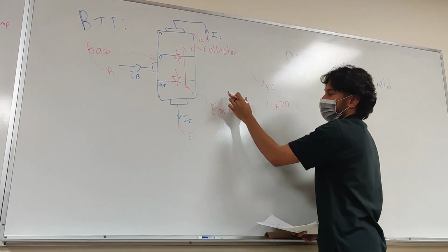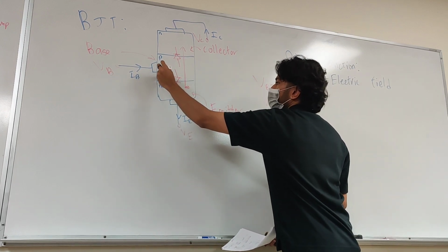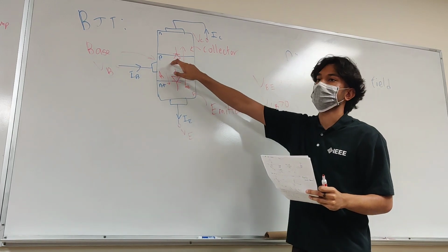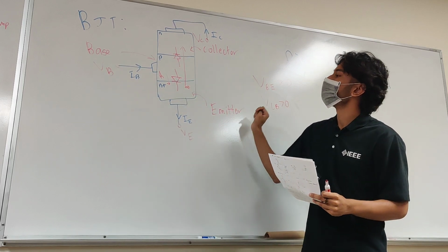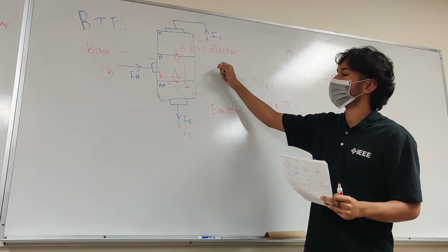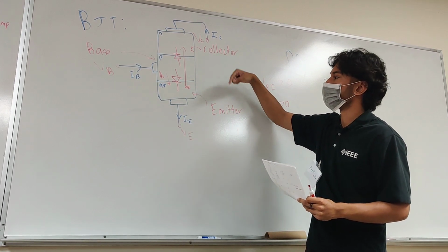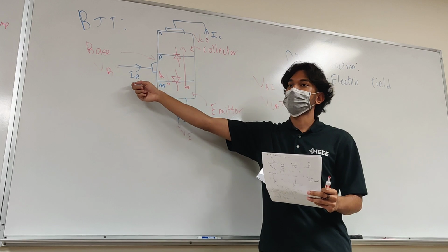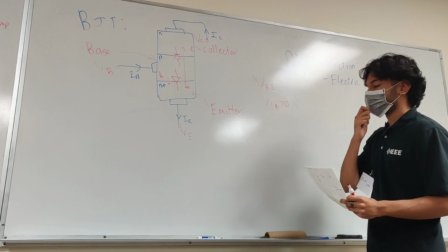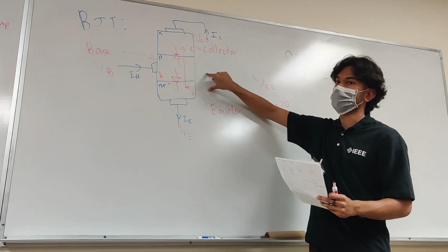This emits the electrons. We have some holes going this way, okay? But these holes end up recombining with some electrons here. And if you're not familiar with recombination, that's fine. But what happens is these holes kind of disappear, and that's bad. We want to kind of always have a supply of holes, so our concentrations are the same at all times, so our device continues to operate. That's what this IB does. It supplies positive charge here. Okay? The details aren't super important, but that's the reason why we have a certain IB that we supply to our device that can maintain this equilibrium in a way.